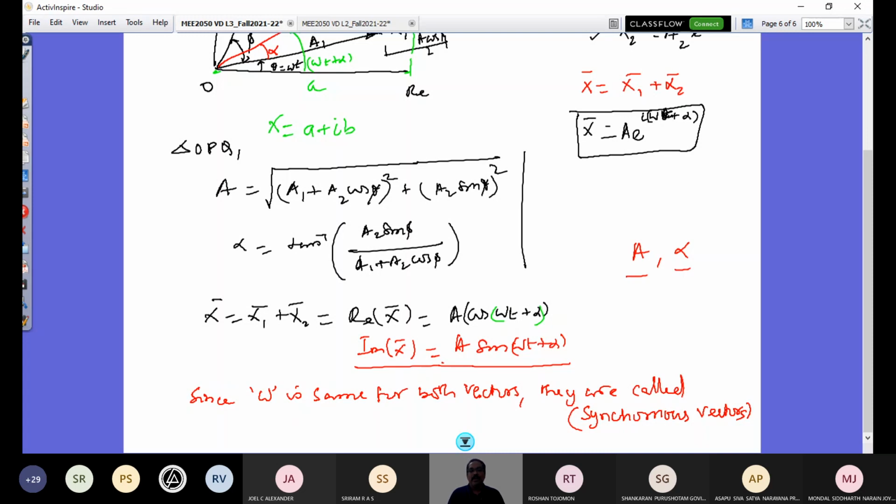So whatever we were doing today and last class are all confined to free vibration, because they are only induced by an initial condition. And it is very interesting that the time period and natural frequency you have defined are independent of initial conditions. They only depend on the mass of the body executing simple harmonic motion, not even the weight, because g is constant. So the mass of the body and its elastic property are what dictate the time period or frequency. Initial condition is of no matter.